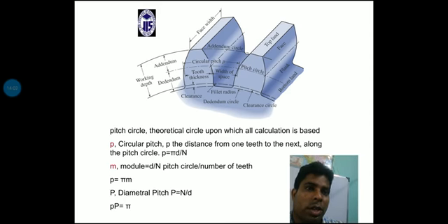The pitch circle dia is at the center line crossing point. Above the pitch circle dia, that point is marked as the addendum, and that circle touches the top of the teeth face.